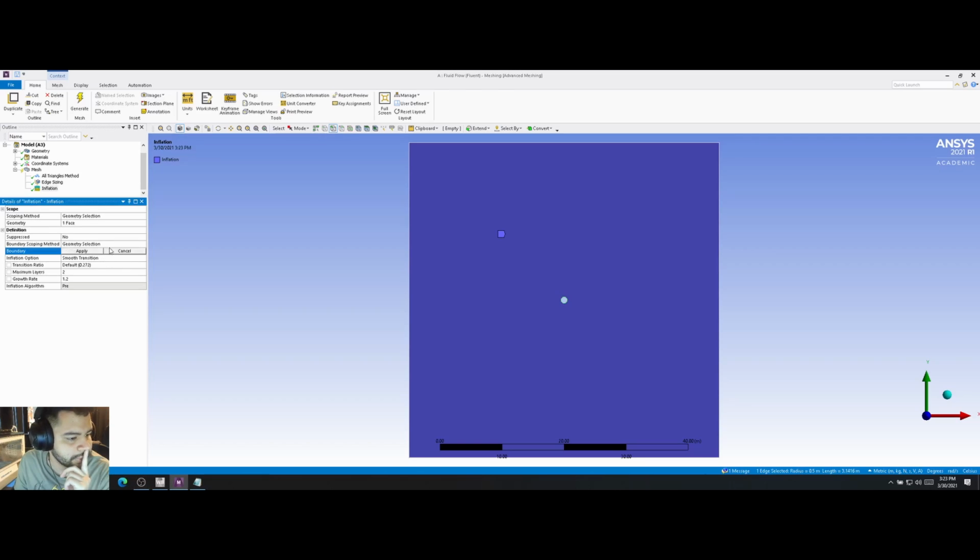For this part, we're going to have to select the first layer of thickness, and for this part we're going to go for, let's see. What I'm going to put here is, let me see what I did in my previous case. I put an inflation thickness of 0.02, for example. Like here, I define 0.02, okay? And maximum layer, I put 100. Let's see, 0.02. And here we go 100, and here we go for 2.5.